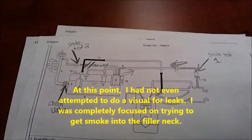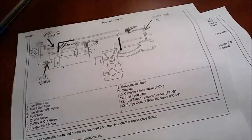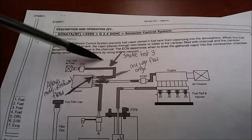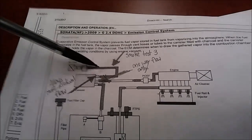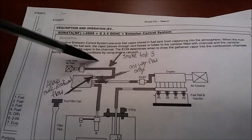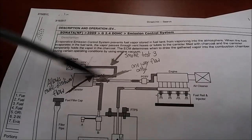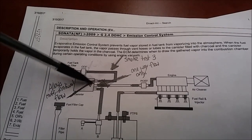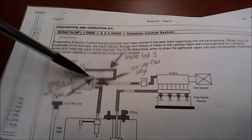So what we did after that is we changed our test location again, and I'm just going to go to this other diagram. What I ultimately ended up doing was I disconnected this hose from the vent valve, and I put my smoke tester in here, and I pumped smoke in this direction back into the canister. And that's when I actually started looking around for leaks, and that's when I found the leak in this canister. To be honest with you guys, I think this was a mistake on my part.